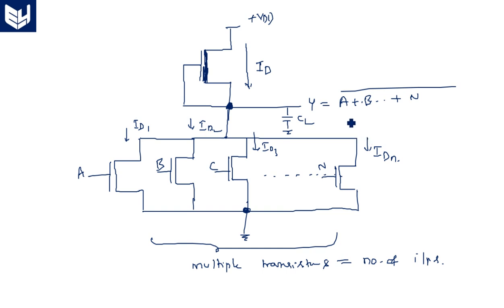Okay, and there is no switching action for the depletion mode transistor. Don't forget that. It is NMOS depletion mode. Because the depletion mode transistor is always in on state, the static current flow is always available at this node. Depending on the on off conditions of the bottom transistors, the current flows.